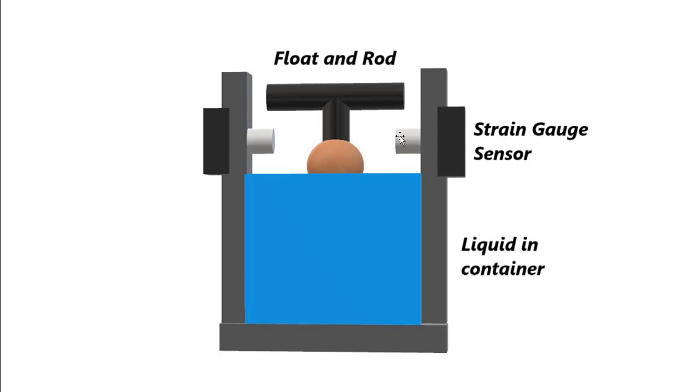The change in resistance contributes to a voltage or current signal. This is a single sensor arrangement where only one level alarm is there. Generally it is the danger level, where we don't want the liquid level to go above a certain level or below a certain level. So it generates an alarm for only one level because only one sensor is used.